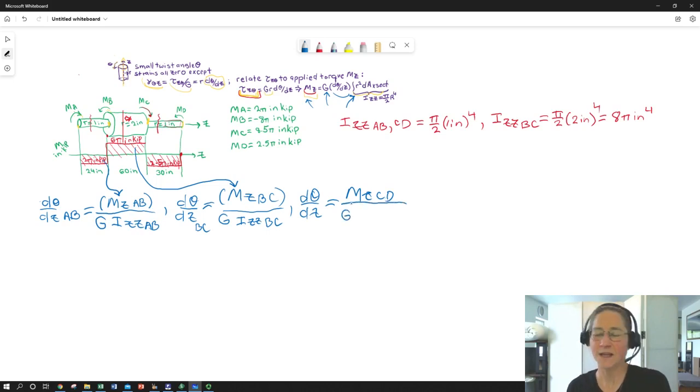Material hasn't changed. It's very rare, by the way, to get a change of material. For something like this, you could maybe do a butt weld and weld one material into the other. That gets dicey. In addition to the defects that you can have, there's a lot of issues with material mismatch. It is possible to have something like that. Generally speaking, when you're designing, you will always want to avoid abrupt changes in anything, whether it's dimensional changes. We saw the effect of that on stress concentrators. You certainly want to avoid sharp corners. Those are deleterious in addition to a section change, but you also want to avoid big modulus changes.